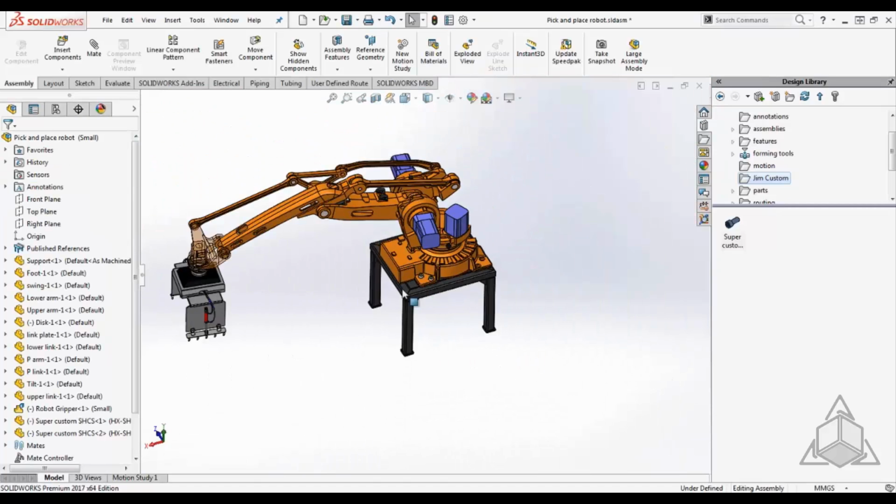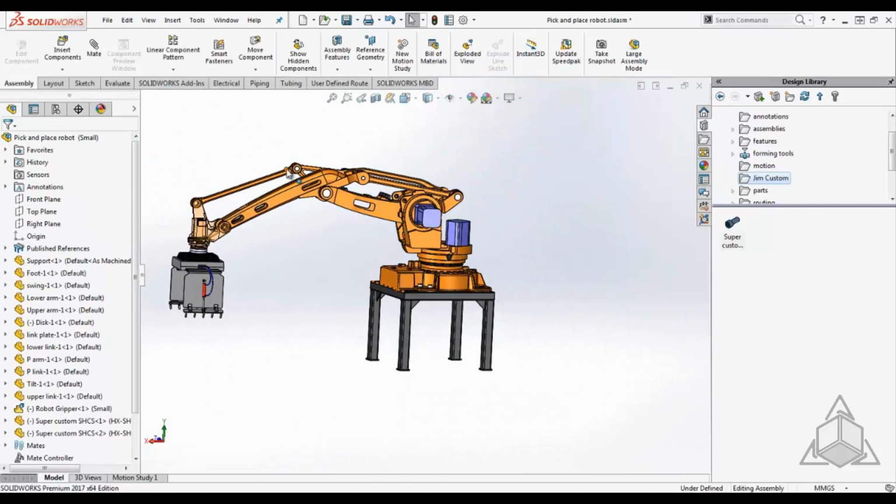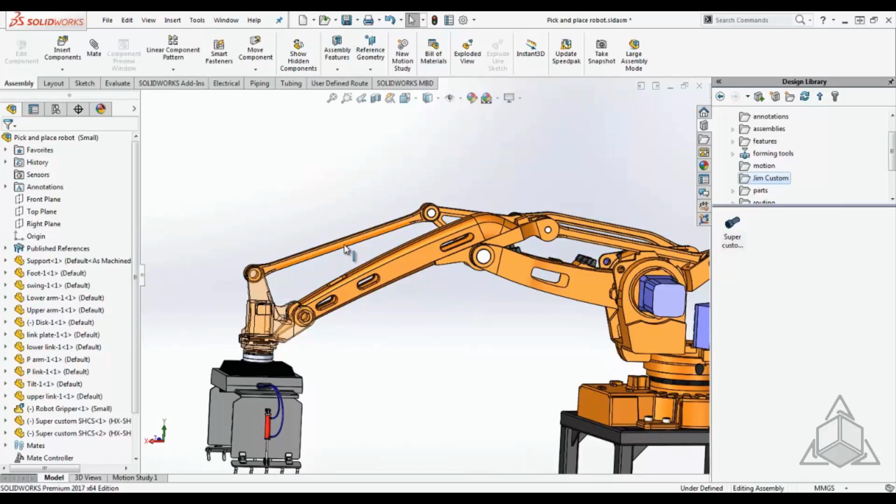For my second tip, let's talk about hiding components. A few years back, we gained the ability to use Tab to hide components. Just hover over a component and press Tab to quickly hide any component. To unhide the components, hold Shift-Tab and move your mouse to the location of the hidden components. When your cursor touches one of the hidden components, it will become visible again.